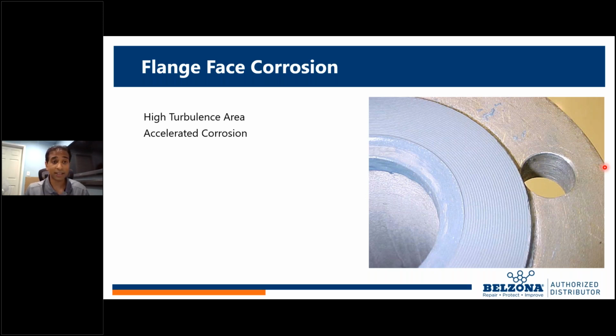In the event that the corrosion has happened, which again, we want to be preventative, in this case, I'm going to talk mitigative only this once, we can actually rebuild that flange face in situ, meaning we can do it in place. We're not going to use hot work, and we're going to be able to get you back up and running fast.